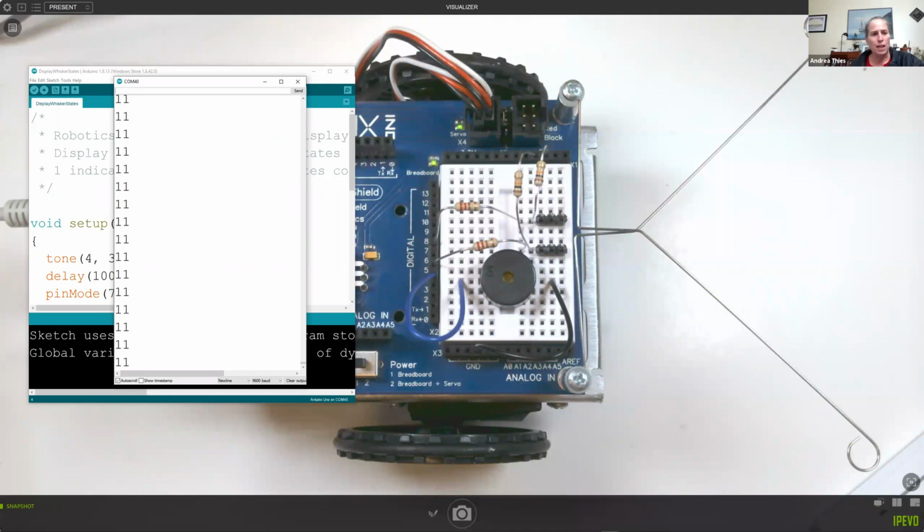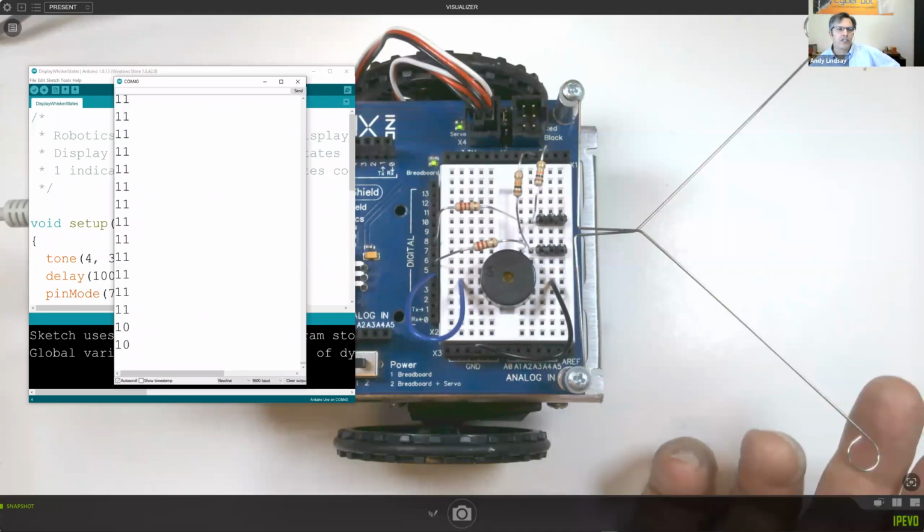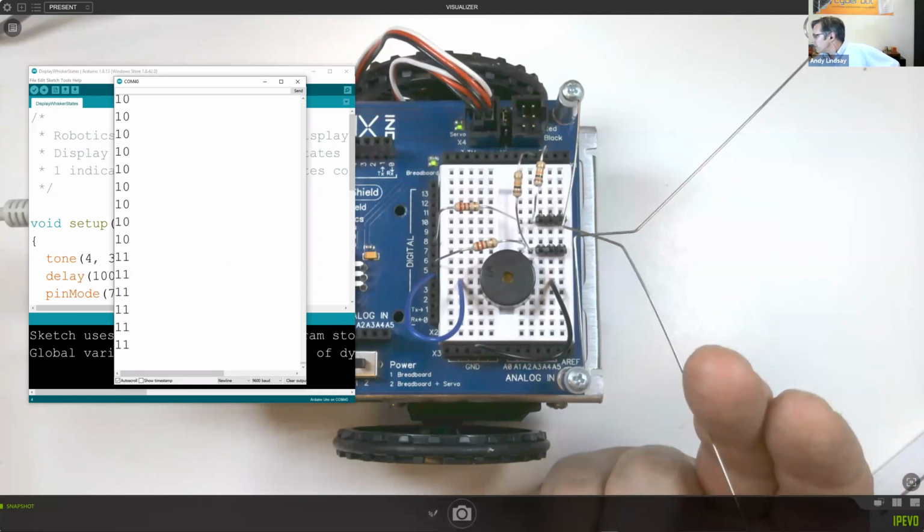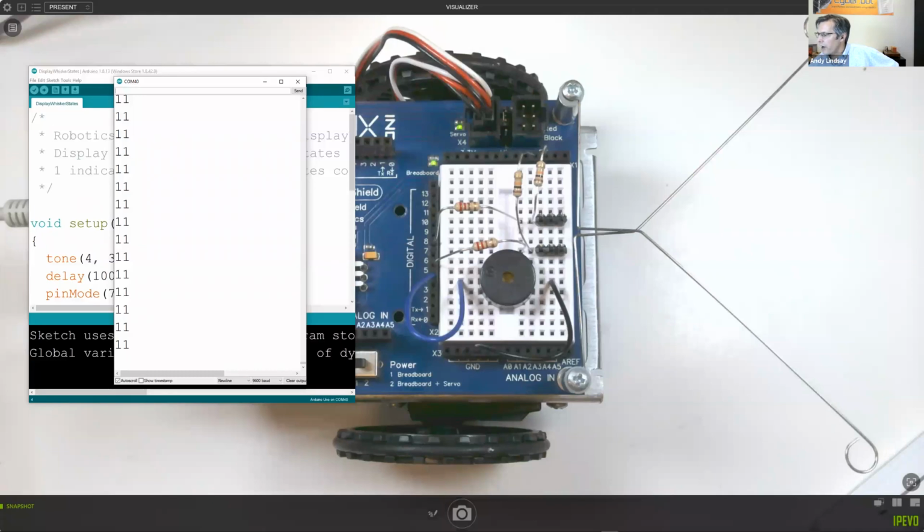Okay, and you're saying if they're both touching, then you get a 1-1? If neither are touching, you get a 1-1. Oh, okay. Yeah, the technical name for these switches is active low, meaning that when you've pressed the switch, the signal goes low. And that, by the way, is because the chassis is grounded, as in connected to the negative terminal of the battery pack.